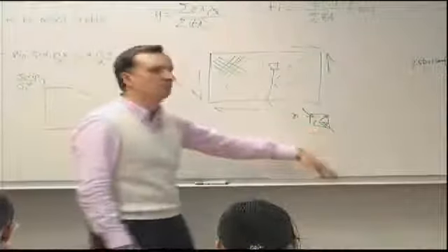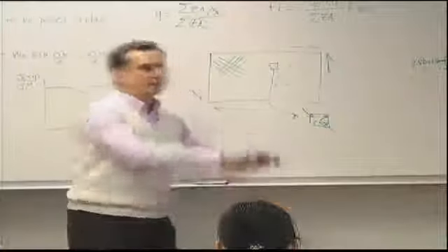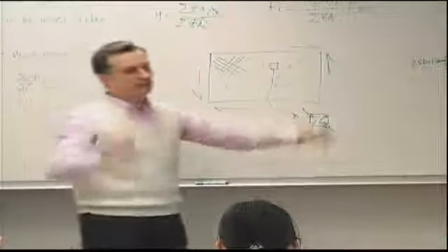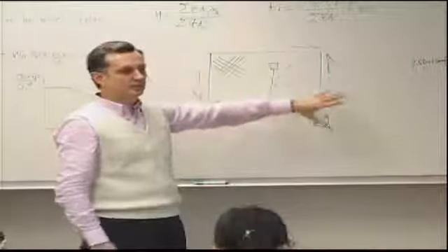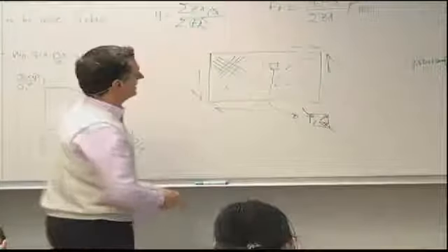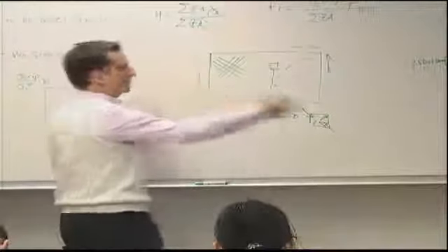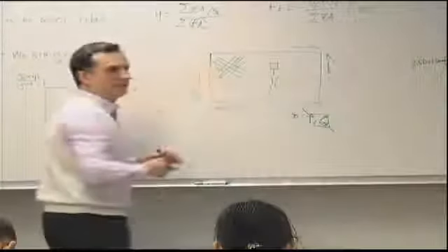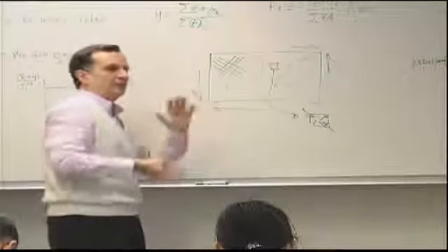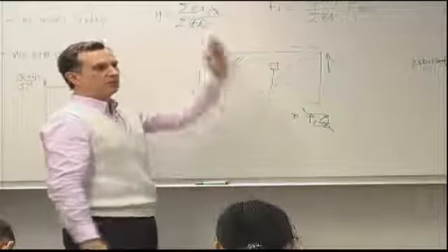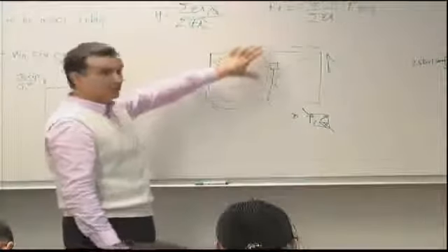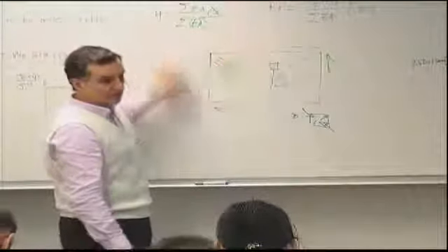Even if you removed completely the matrix and you had all these fibers and you were pulling in tension, you would have a phenomenally good performance. This doesn't happen in a pure compression case. Pure compression, no matter what your layup is, you will not achieve a part of the structure that's completely in tension, and that tension load would be the majority of the applied load.